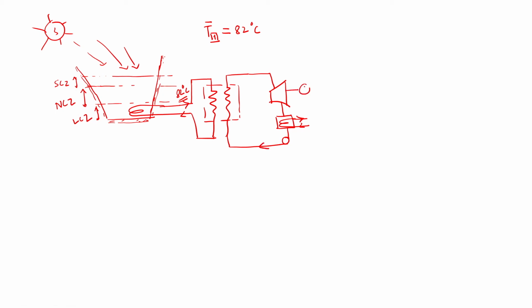So what we will get, this is 18 kilowatt. This is the turbine, this is the condenser, this is the pump WP. Pump work is neglected here, and this is the heat exchanger. So this hot water goes into the heat exchanger and exchanges heat with this organic fluid, and then the fluid will be evaporated, or refrigerant will be evaporated, like ammonia, which we have used in this setup, or maybe other refrigerant, R22 can also be used.